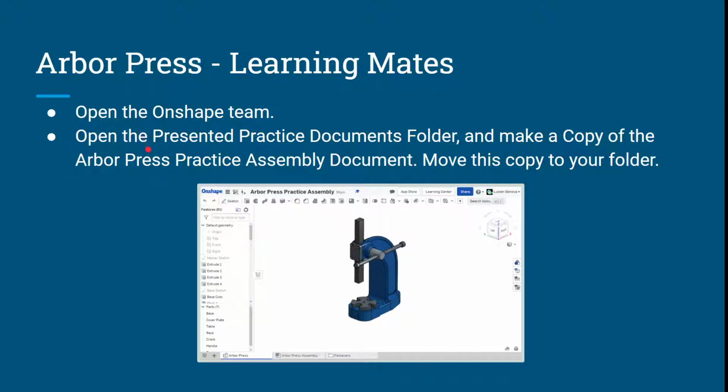So as we're getting into mates, basically what mates do is they take these points called mate connectors. A mate connector is a point that Onshape decides, or that you can choose on your part. A mate connector is a point, and it has 3 axes, and you can connect it to another mate connector and give them different restrictions between degrees of freedom. So you can say this mate connector and this mate connector are completely fixed together, so there's no degrees of freedom between them. Or you can say this mate connector and this mate connector are rotational to each other. So one is fixed and the other one could rotate about one axis, let's say. And there's all different sorts of mates that can give you different types of degrees of freedom.